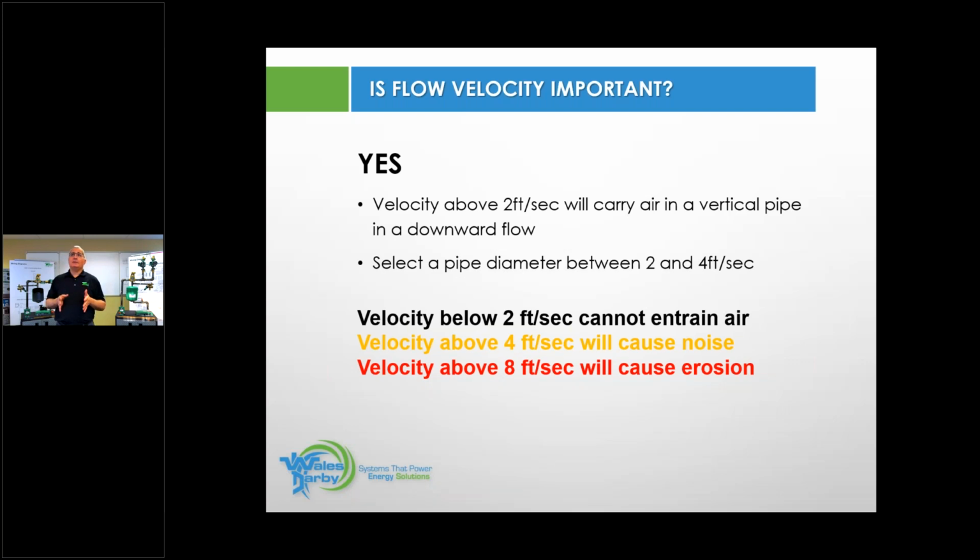And also one other thing to think about, if I do a crimp fitting versus an expansion fitting, there's really only one way to do it, and there's a perfect visual to show you that it's done correctly. The shoulder of the fitting to the shoulder of the ring would be right against each other. On the crimp side, now I'm not bashing crimp at all, but I'm just telling you, there's too many chances of that crimp ring being either in the middle, toward the front of the fitting, toward the back.